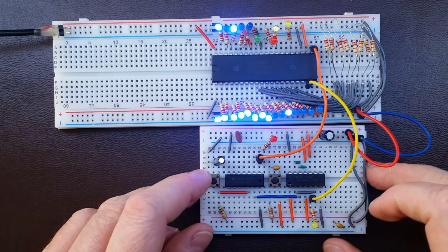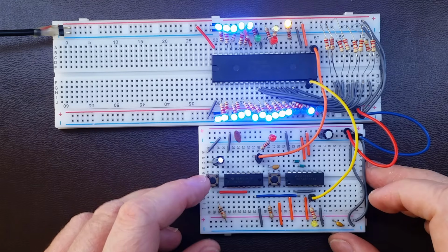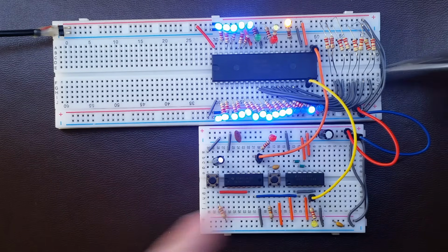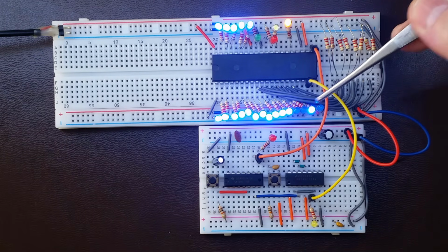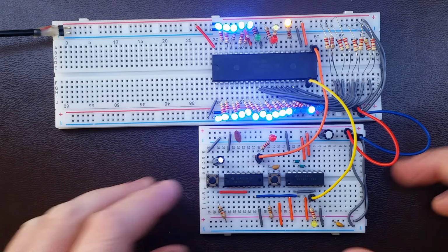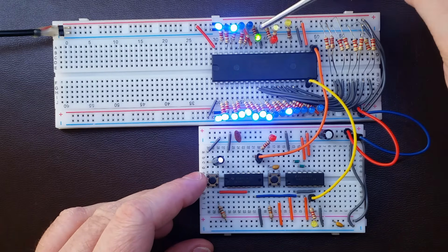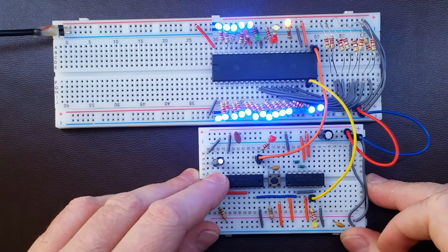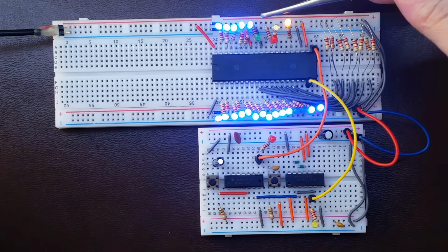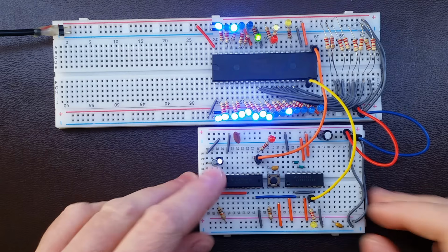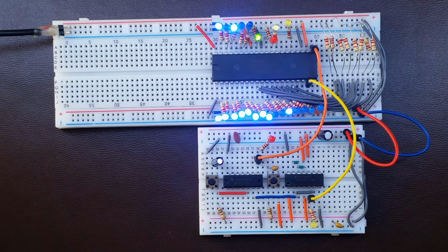RD is now inactive, and that is the third fetch. And as you can see, now the CPU tries to read from FFFF2, so it tries to fetch yet another instruction from our memory. Now it has read it, and it goes to yet another fetch. Now we've got FFFF3 addressed, and it's a read, and of course it reads another NOP.